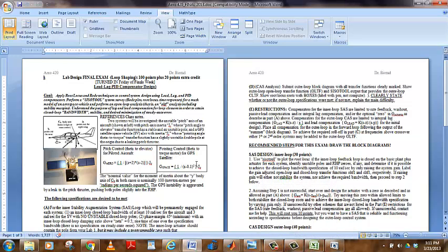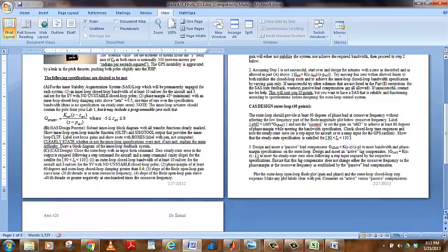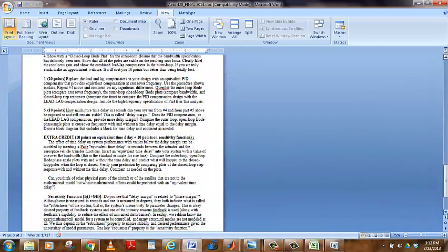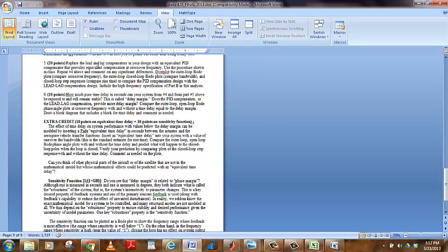You assume that you had an actuator, and of course you're going to feed back your pitch rate from your gyro. If you fed back theta and made the problem easier, that's okay, but it would have required some discussion and probably cost you some points if you didn't convince me. 40 points for the cast design. Almost everybody got the cast design fine. We had the replacement of the PID, and very few groups showed me how they replaced their PID compensator, so that might have cost you some points if you didn't show me how to do that.